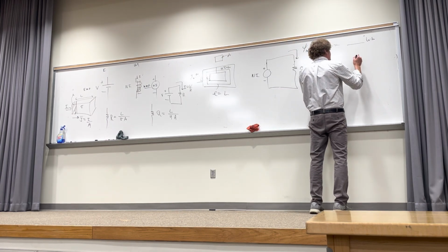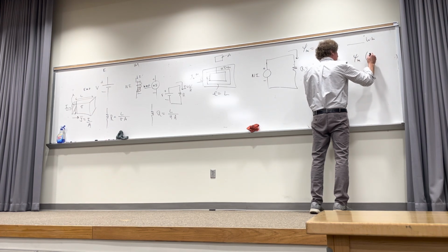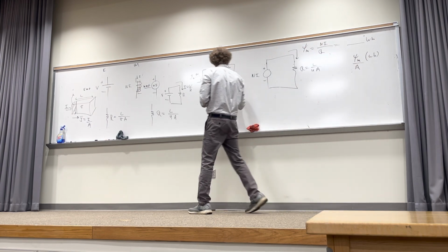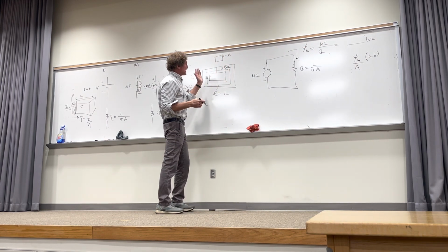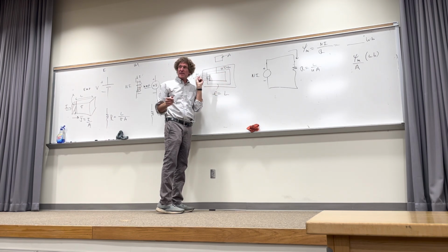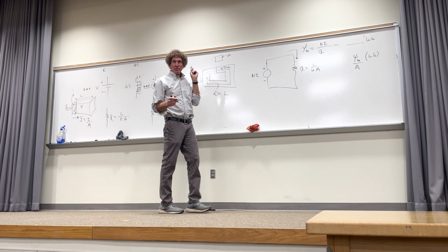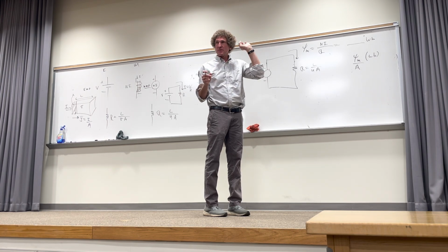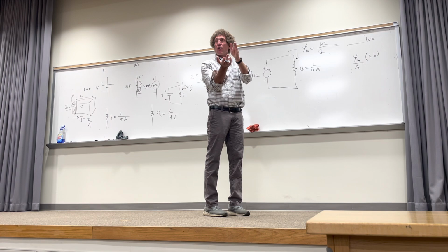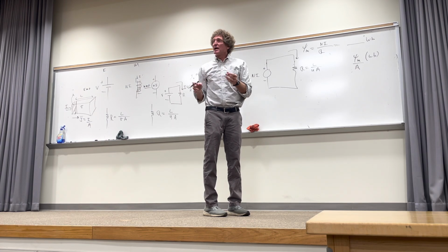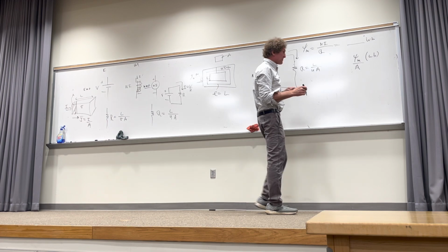If we take the magnetic flux in Webers and we divide it by the cross-sectional area that it's flowing through, it would be the cross-sectional area of the bar. Now, I made this bar very easy to understand. Constant cross-section, it's got one total path length to worry about. But it could be different stages. You could have a bar with a different cross-section or different material. There could be an air gap. All these things would make the problem a little more complicated because you would have to account for the magnetic resistances associated with each point. But nevertheless, the same basic phenomena goes on.